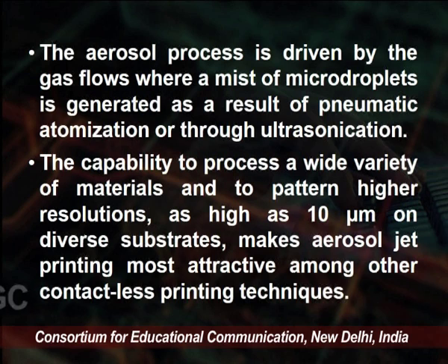The capability to process a wide variety of materials and to pattern at a resolution as high as 10 micrometers on diverse substrates makes aerosol jet printing the most attractive among other contactless printing techniques. Moreover, aerosol jet printing is divided into two main categories. One is pneumatic, another is ultrasonic. Both techniques are based on different operational procedures and target specific sets of requirements and goals.